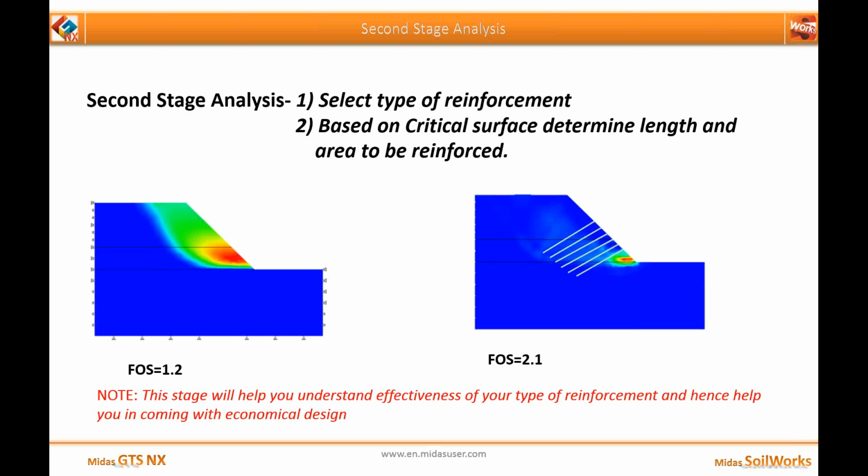Okay, so I will just open SolidWorks once again. So now I know what my critical area is, or which area I need to start reinforcing so that I can reach the factor of safety of 1.75. Now, as you have already seen, the factor of safety was 1.2.